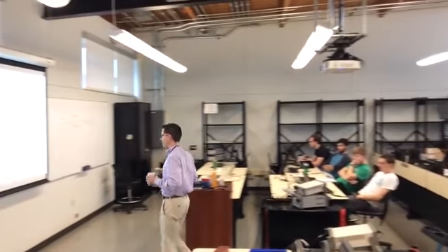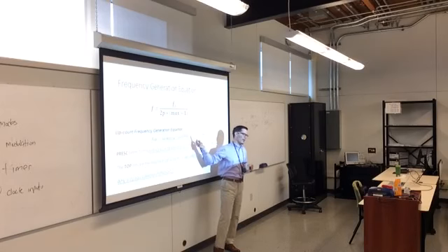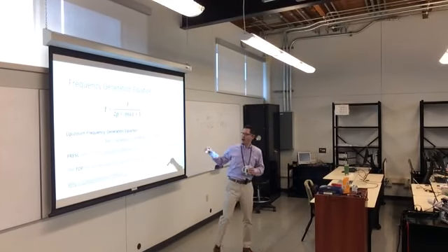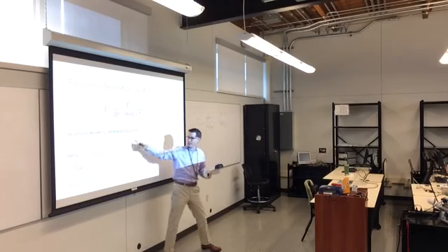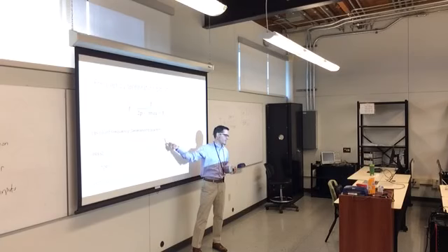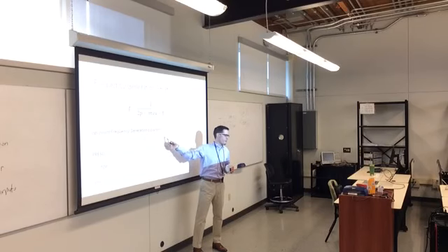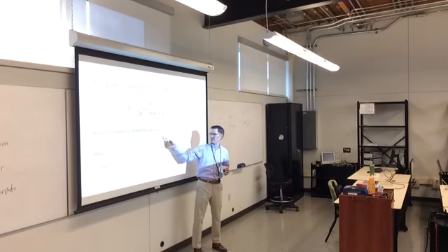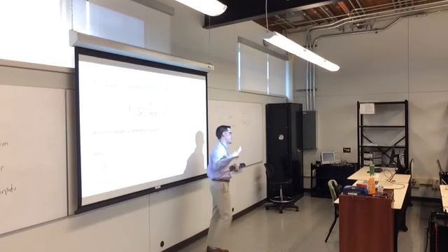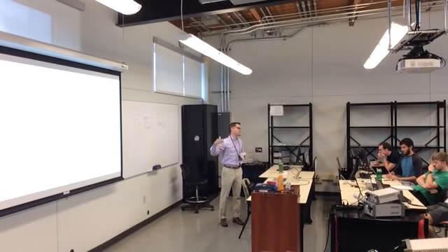Here, they are representing the prescale as raw bits that go into some register's configuration. So in the application notes, you will find expressions like this, and this is a raw number, but it is actually some sort of configuration bits. If it's printed in all caps like that, it's a binary value. Inside the data sheet, if you put a 0 for the prescale, it becomes 2 to the 0 plus 1, which is the same as not scaling the clock. So for them, prescale bits of 0 means do not scale the clock.